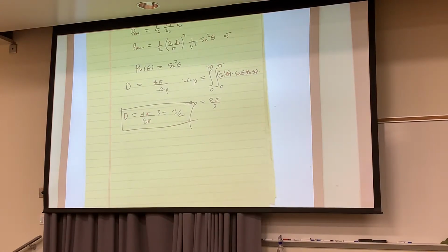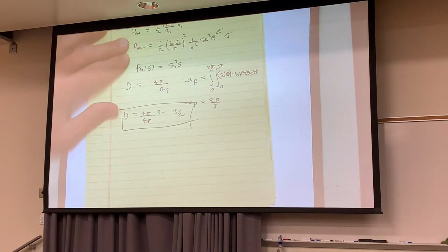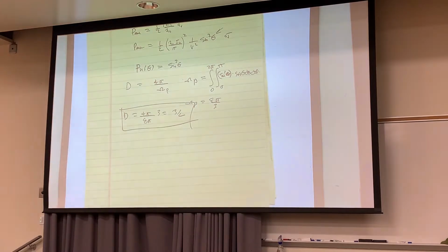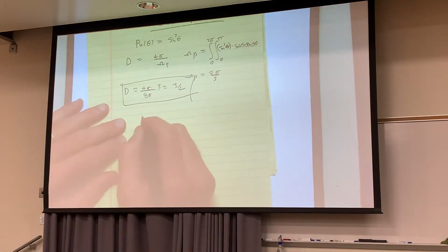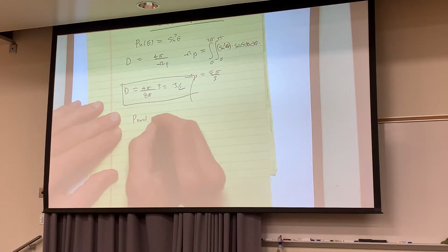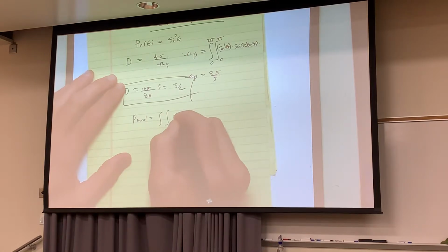Now the radiation resistance, you can do it a couple different ways, but since you have the power density here, this is the brute force way. This is the average power density, isn't it, right? So if we multiply that by a differential surface element and just integrate over the surface of a sphere of any distance r, we would get the total power being radiated, wouldn't we, class? You remember doing this? Sure. So if I take this right here, P_rad is equal to the double integral of this, P_av, which is, I'm going to try to write it down. I do not like using this because I'm bending my neck and it hurts.